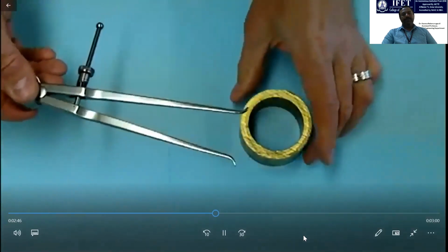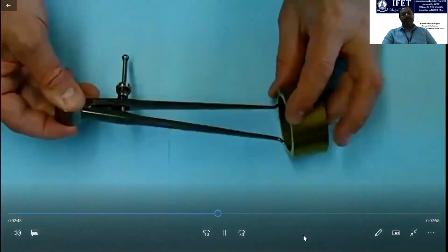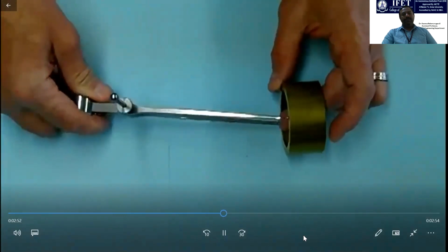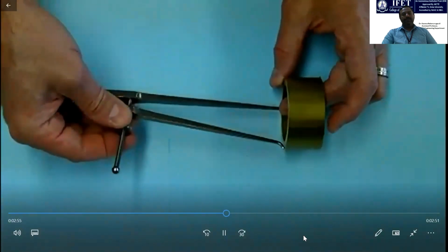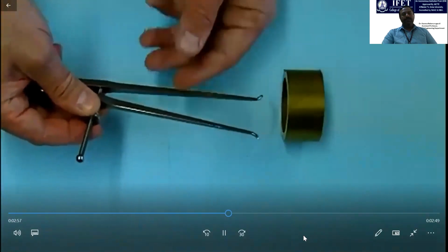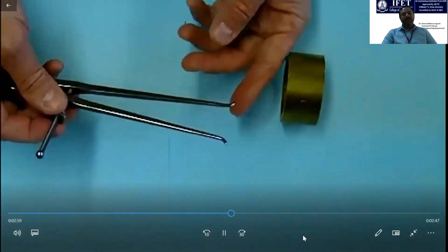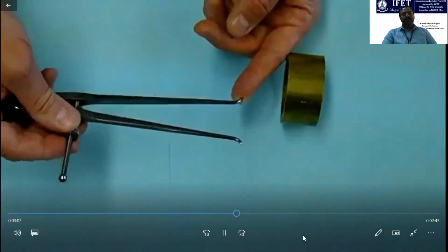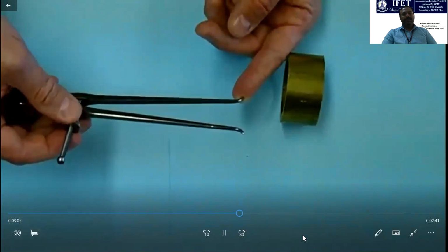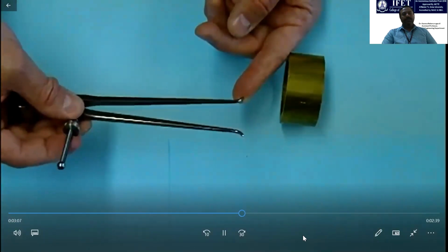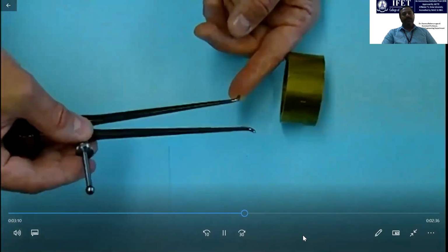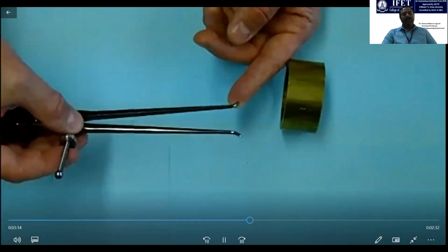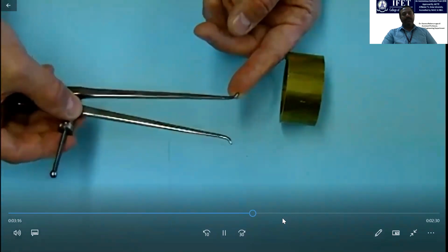How this works is I would set it inside a bore on the one leg, and again, I would be adjusting the nut up top. Now what I want to do in the bore, as I'm adjusting the nut, is have it sit against the one surface of the bore, and wiggle the top one back and forth as I'm turning the nut. I also want to have the caliper go into the bore and back, and just feel the highest point until it just drags.